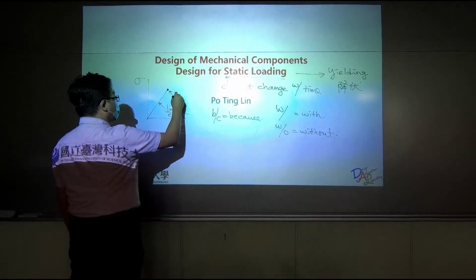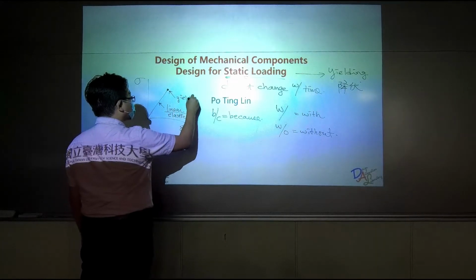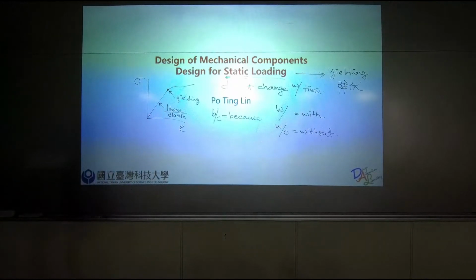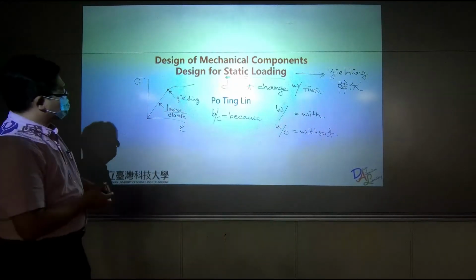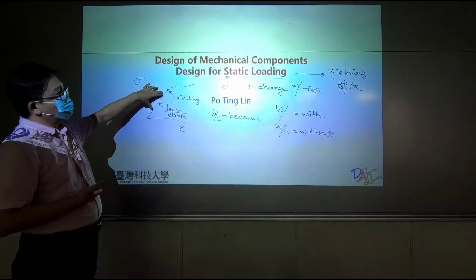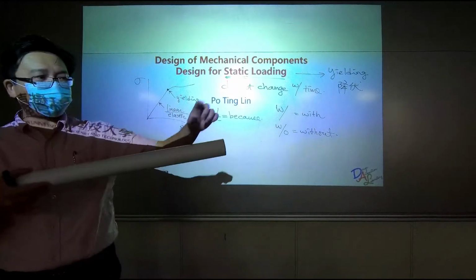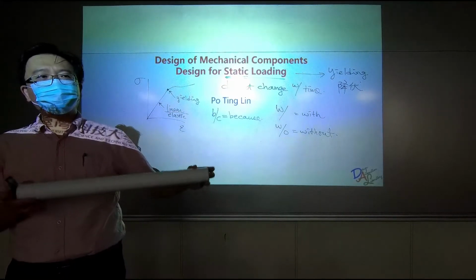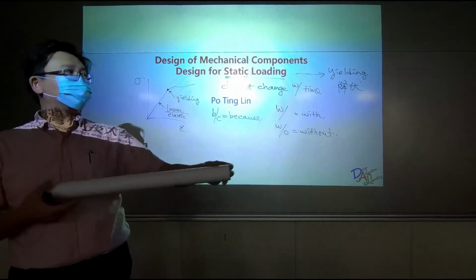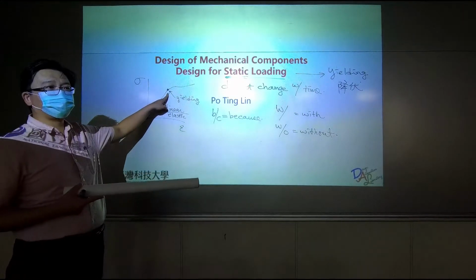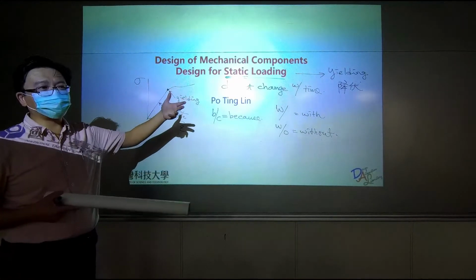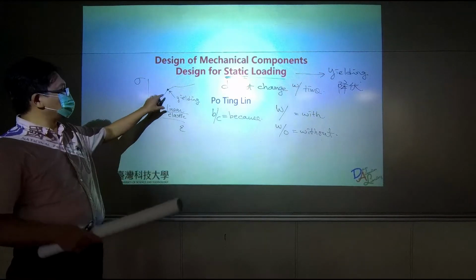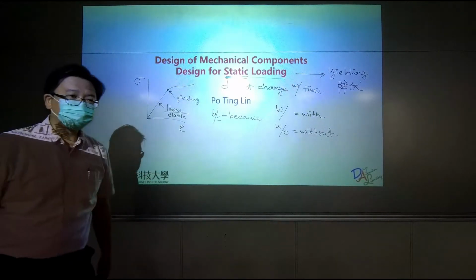When we pass the yielding point, we have nonlinear deformation and it doesn't recover. So when it's under a static load, the first possible failure it could face is yielding. If yielding happens, it's a failed part. So for static loading, we worry about yielding.